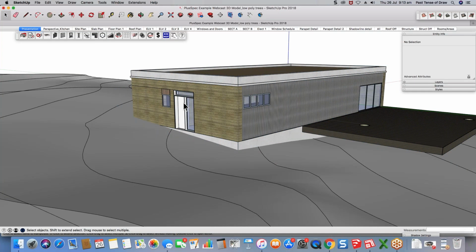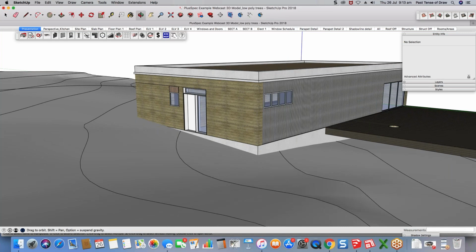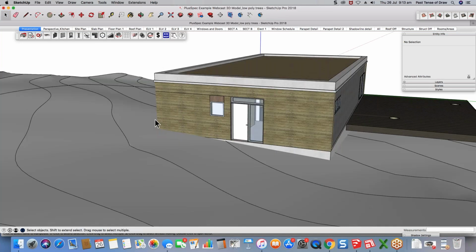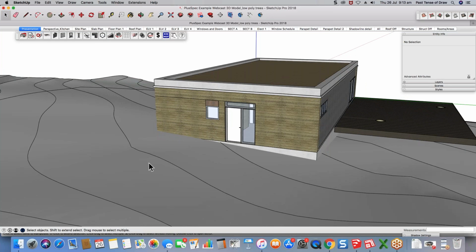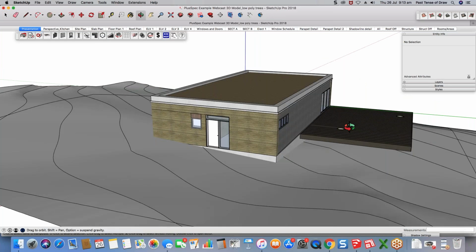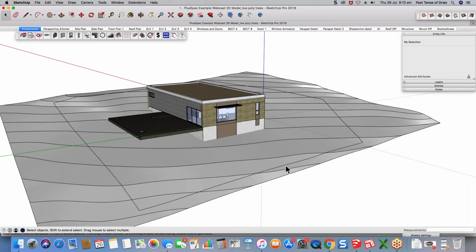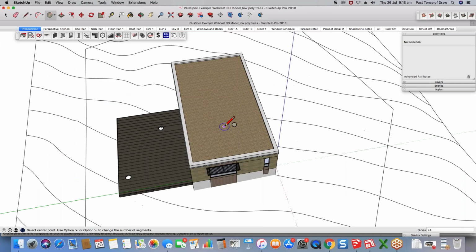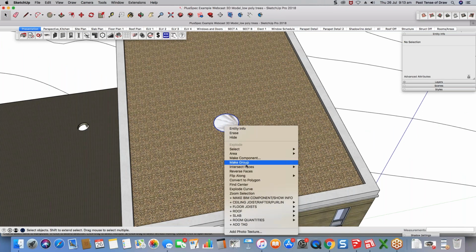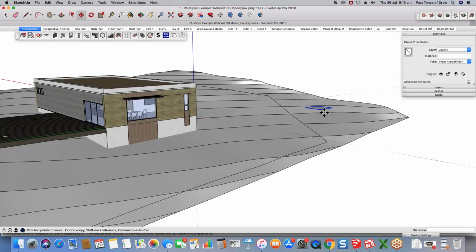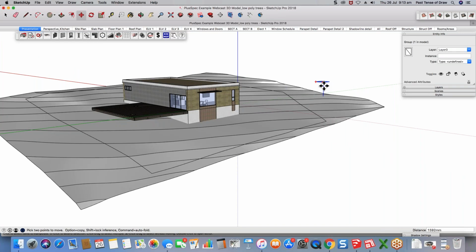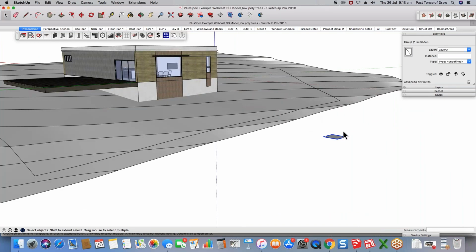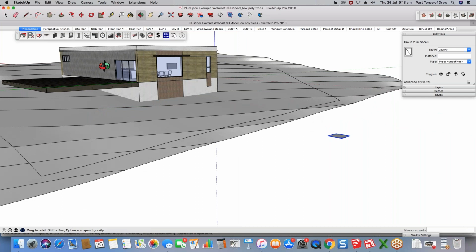And that's what's giving you the ability to position it. Now, for example, if you had a datum and you knew that you would include the datum somewhere in your model, and typically, if it was a site surveyor's drawings, it's shown with some kind of symbol. For example, I'll just make that like that, and I'm going to move it. And your datum in the CAD drawings, when you brought it in, would already be at the height. So it would be some height in there, and you would know what the height of the datum is, and that enables you to calculate the height of where your slab is.